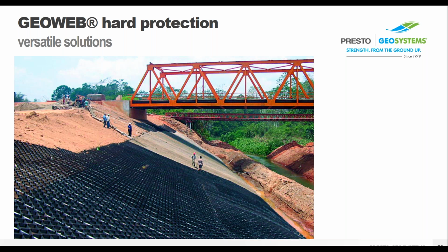That's the big issue with pouring concrete on a slope, is how do you have that flexibility of, well, you need a little bit more water to make sure it actually flows, but it can't be too wet, because otherwise it's all going to slump to the bottom. With the GeoWeb system, that's not a concern. You can actually have a little more water within your concrete, and it'll still be contained within the GeoWeb cells and not slump to the bottom.